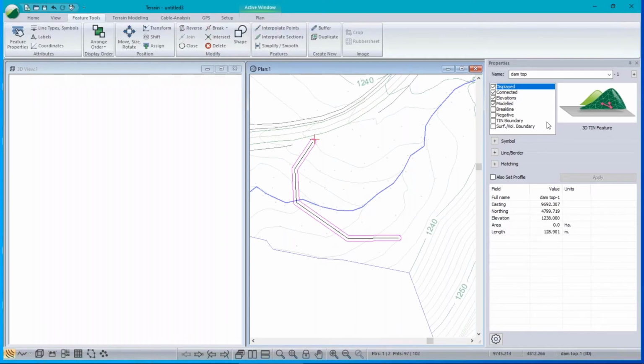And it's going in the clockwise direction. You can tell because if I do Control N, it jumps along the feature in the clockwise direction. That's important for the next step. Now that thing's sitting at the right elevation. It hits the ground here and it hits the ground over there, but it's up in the air along here because it's higher than the ground surface.